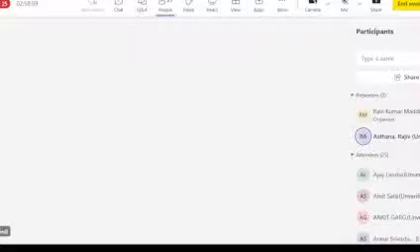How to make these kind of very thin ceramic plates? If you look at the scale bar, it is 300 micrometers. So this is the ceramic region, which may be about 100 or 150 micrometer across. These shiny regions are metal. They are deposited by PVD, physical vapor deposition, but ceramic tapes, these kind of thin tapes cannot be made by powder compaction. So tape casting is used for that purpose.